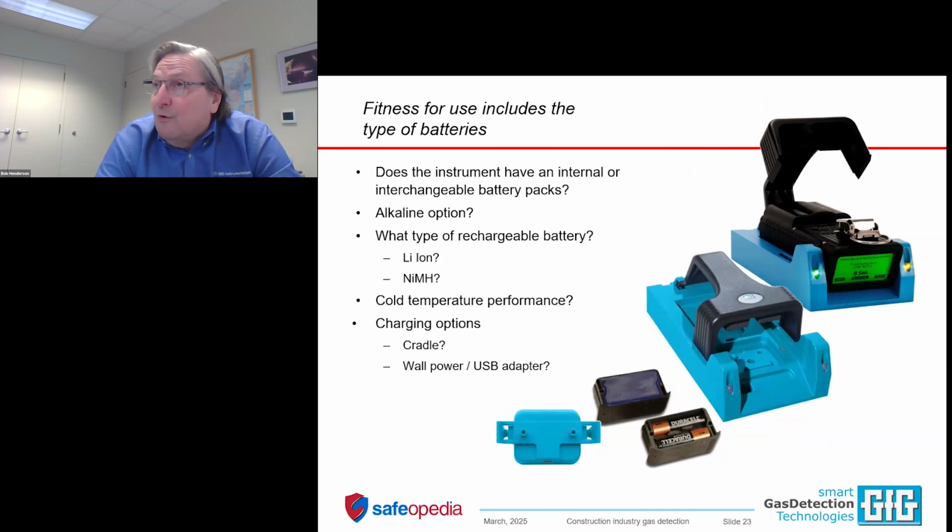They want you to perform minimally a bump check or a calibration check before each day's use. And with regards to performing a full calibration, they leave that up to the manufacturer to specify in the owner's manual how frequently or the circumstances which govern how often you do that. But if there's any doubt, there is never something wrong with the idea of doing a full calibration.